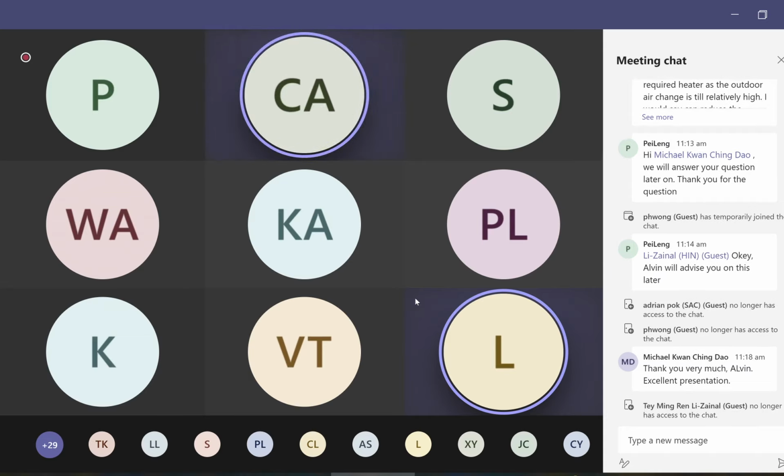Yeah. I mean, if you cannot go too low, then you might have the over airflow issue. So this is how to mitigate. Maybe you need a bypass or what? You don't have an over airflow issue if you are using pressure independent. The only issue you will face is that the noise from that particular VAV box will be very high if the pressure is high.